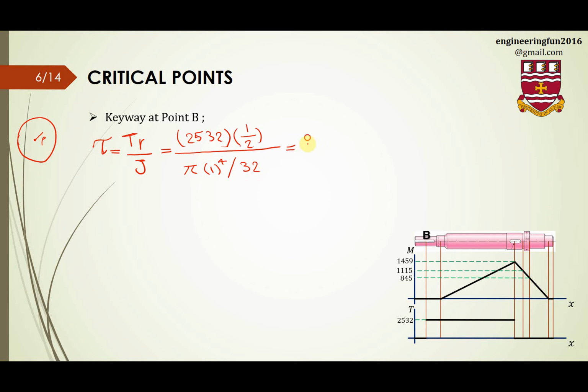So after some simplification, we're going to find 12.9 kpsi, and that's the maximum shear stress at this point. As we said here, because we just have some static loading, we just need to check this based on a static point of view.